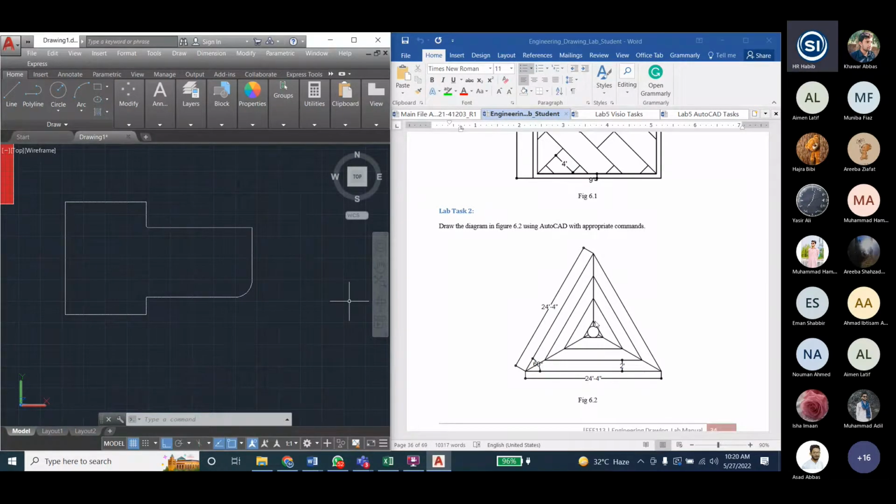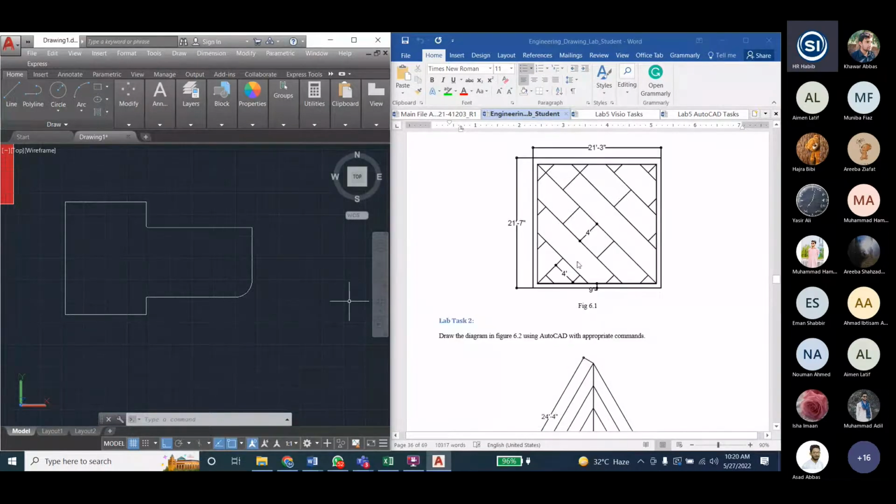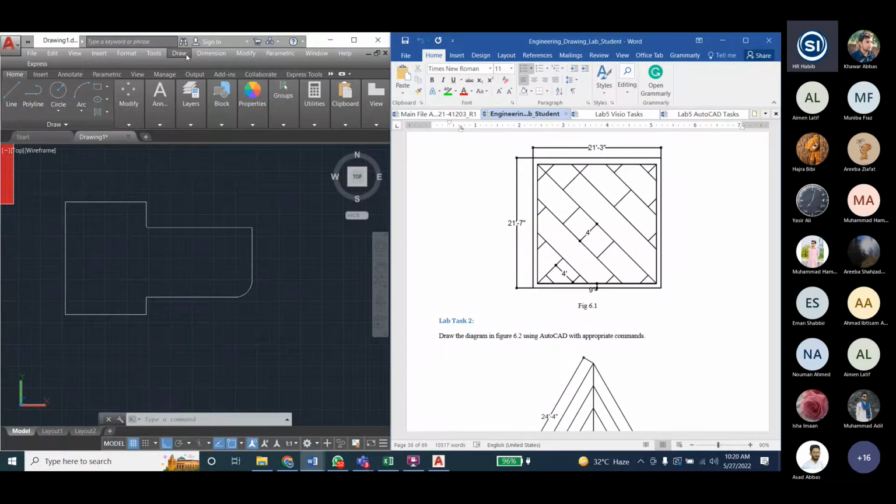Okay, and for this you can use, for example, these simple lines, or you can say one rectangle, and then you can scale it. One rectangle, then scale it, scale it, scale it. It will be easy. And similarly here you can draw the rectangles, as convenient as you can, by your own, with what we have studied so far. You can use all the commands and draw this simple rectangle, and then like that. This is simply the hatch command, which we used last time. This one is hatch, and the distance between lines is 4. So you will hatch the simple lines.